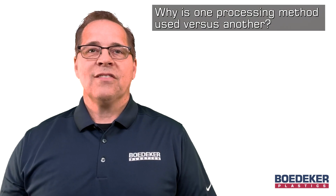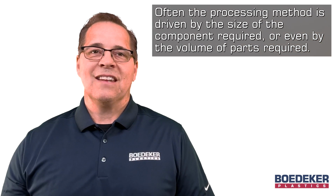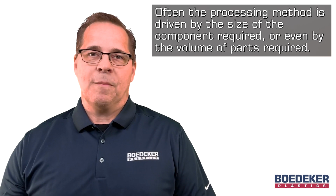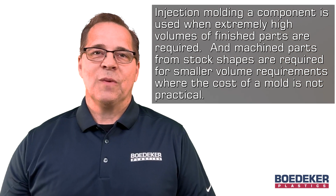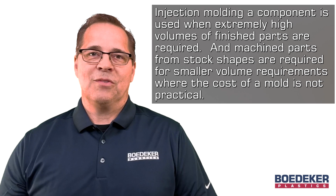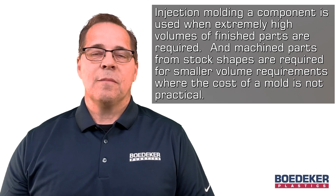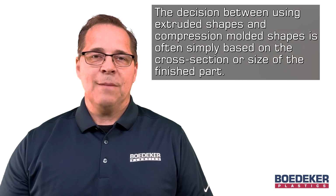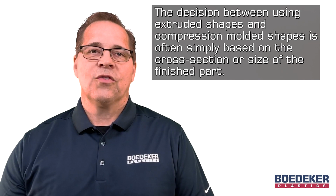Why is one processing method used versus another? Often the processing method is driven by the size of the component required or even by the volume of the parts required. Injection molding of components is used when extremely high volumes of finished parts are required, and machined parts from stock shapes are required for smaller volume requirements where the cost of a mold simply is not practical. The decision between using extruded shapes or compression molded shapes is often simply based on the cross-section or size of the finished part.